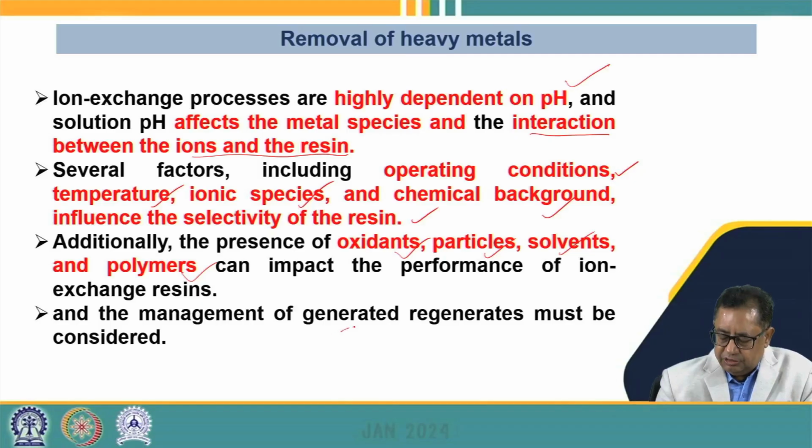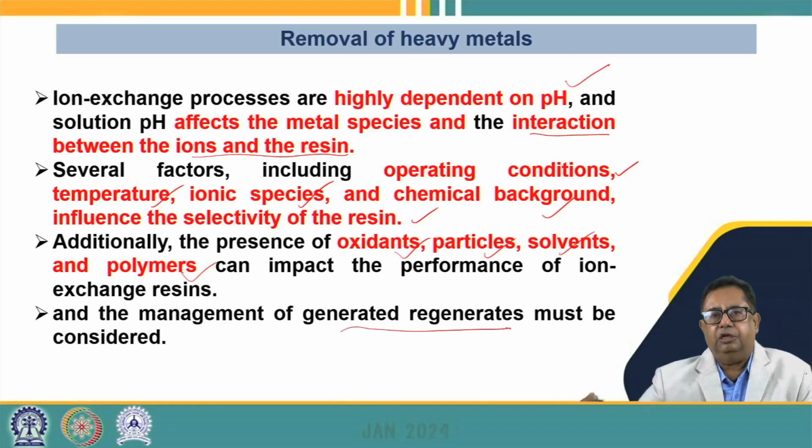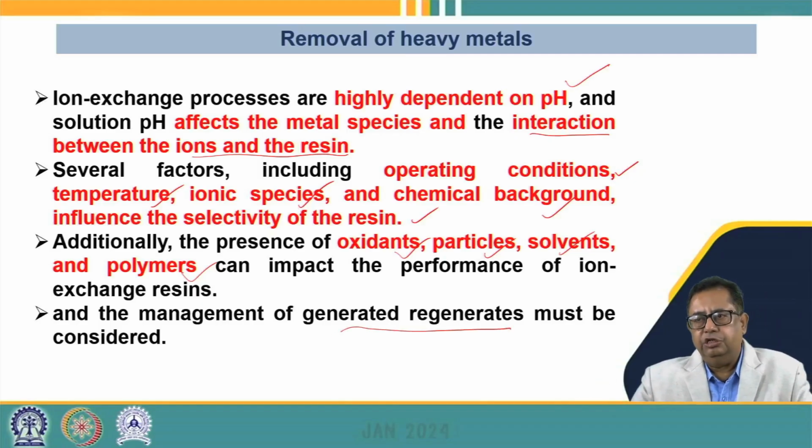And then there is the management of the generated regenerate. When we have the regeneration process, it may again lead to concentrated solutions of the metals or other forms. So we also have to look for the management of the generated regenerates so that we can treat them properly and then dispose of them.